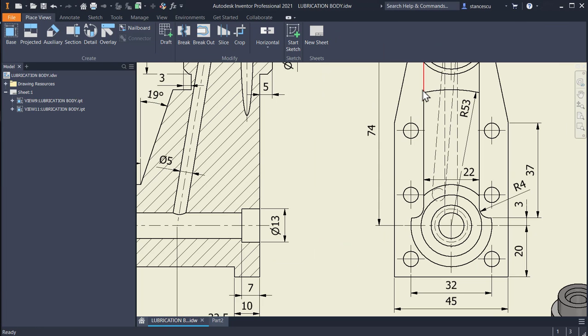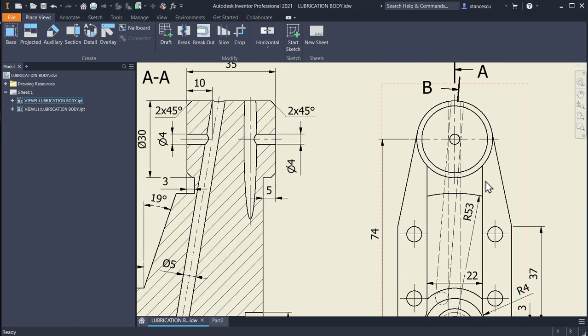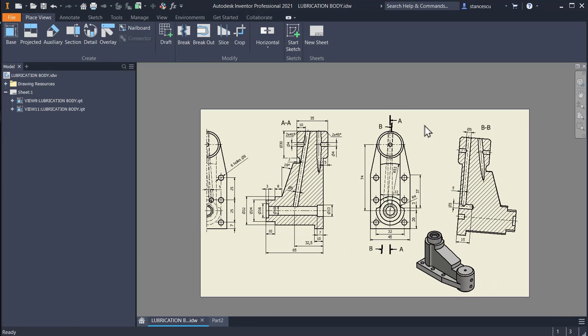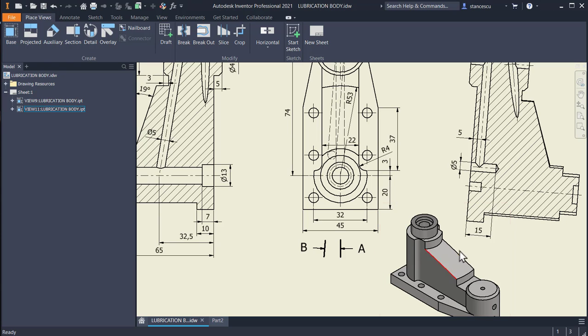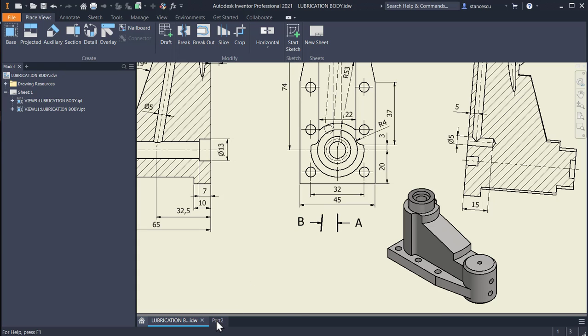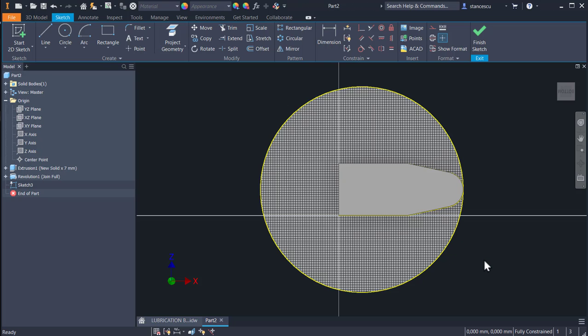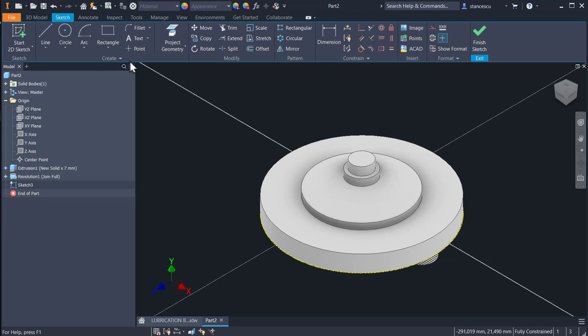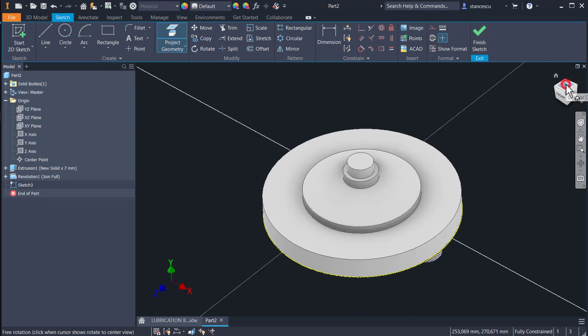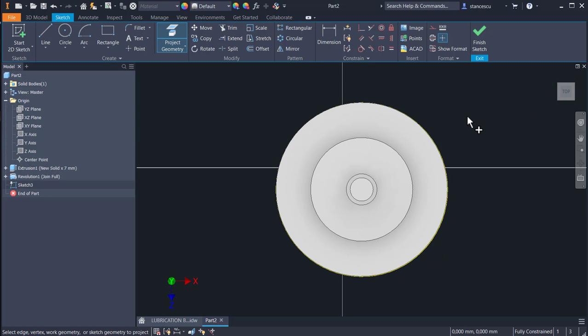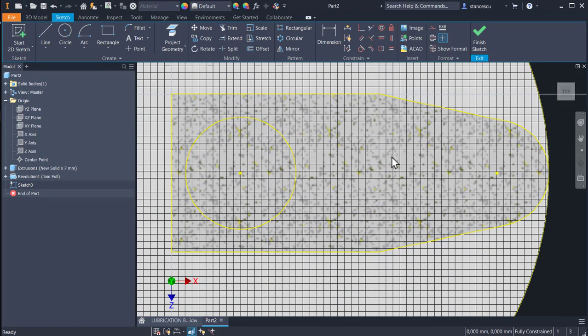Now we have to create this contour, yes, to be placed inside that big round circle, in order to cut the external of this and to remain this contour as a volume. Let's do this. We select this plane for the sketch, but we have to project this circle, and we use this view, F7. You see, this is our space of work.